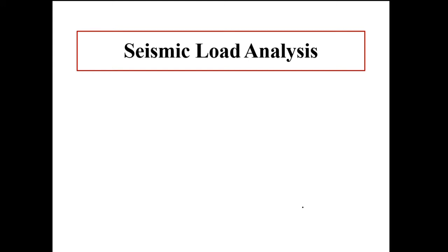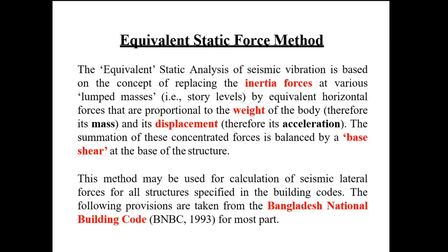So our next topic is on seismic load analysis or earthquake load analysis. Here the earthquake loads or seismic loads will be calculated adopting a procedure which is known as the equivalent static force method. In this method, we will be replacing the inertia forces at various stories of our structure by equivalent horizontal forces that are proportional to the weight of the body and its displacement due to the shear waves that are generated by the earthquake.